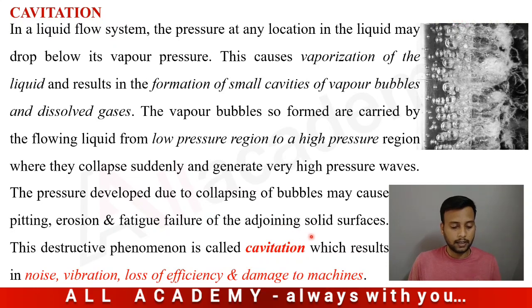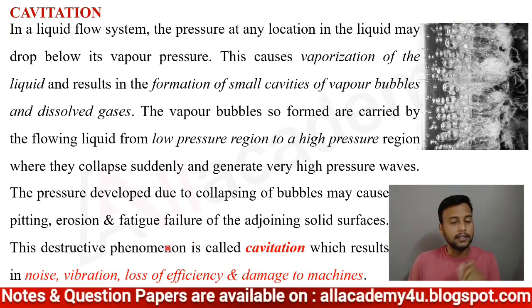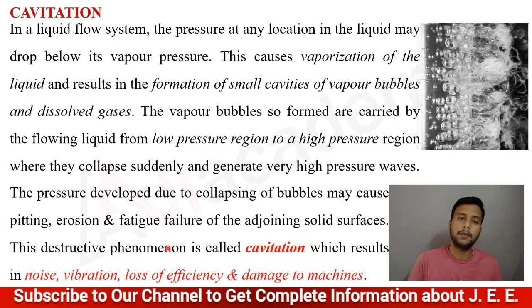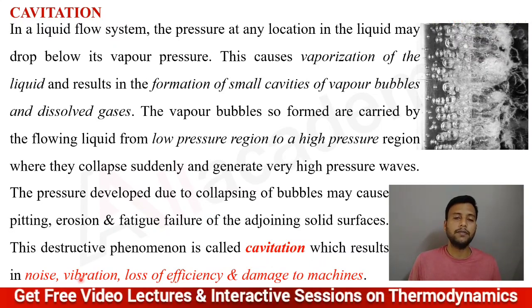So this forms erosion and fatigue pittings on the solid surfaces. This destructive phenomenon due to the bubbles that cause high pressure waves is known as cavitation, which results in noise, vibration, loss of efficiency and damage of the machines.